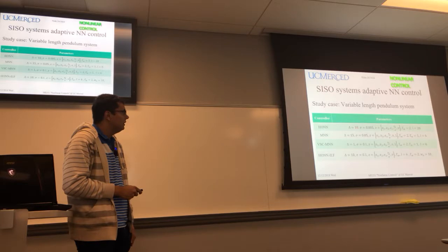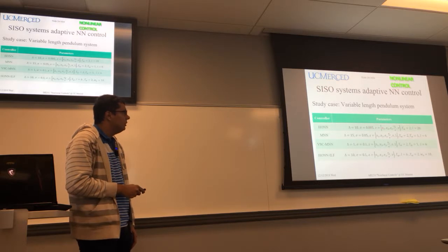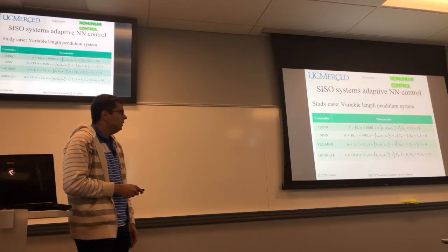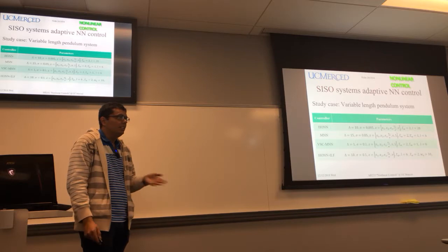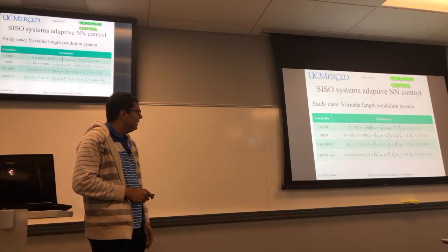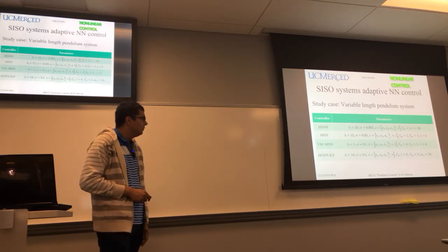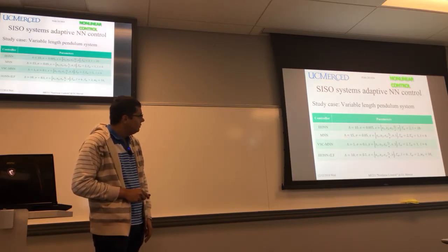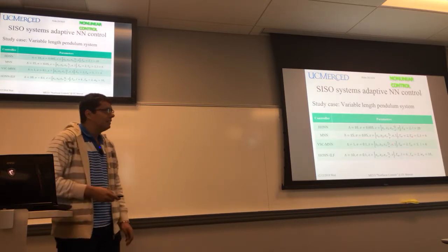In this case, this lambda is for the sliding surface. This sigma is one of the tuning factors of the high order neural network, the input vector, gamma of omega, in this case is 2, lambda equal to 20 neurons. In the other cases, we have 6 neurons, 10 neurons. The amount of neurons could change according to your control technique. Here, as you see, for the multi-layer neural network, we have an additional input, in this case 1, the bias for our application. And in the MNN, we have gamma for W and gamma for UV, because we have two layers to be obtained.